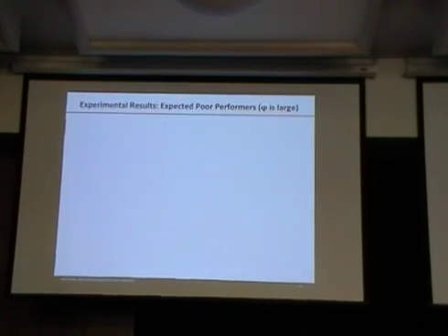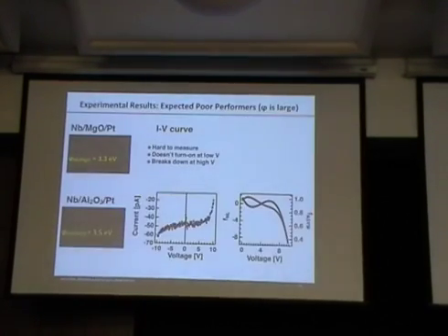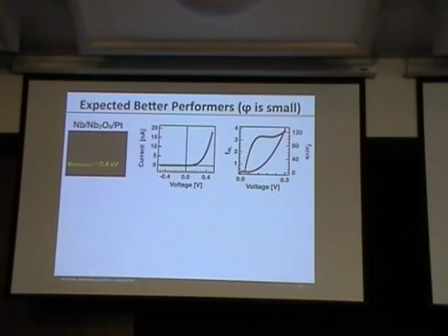And so we can basically begin to put together a material space of choices of work function and electron affinity for the insulators and the metals that essentially maximize the figures of merit that I told you about before. So now, to me, this optical rectifier is an interesting concept because exactly what's happening when we talk about coupling across this insulator at a very fundamental level is an interesting question.